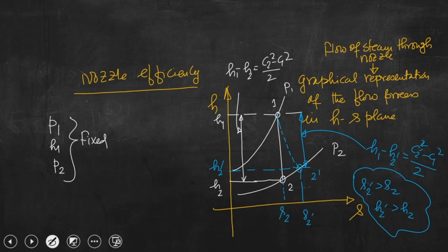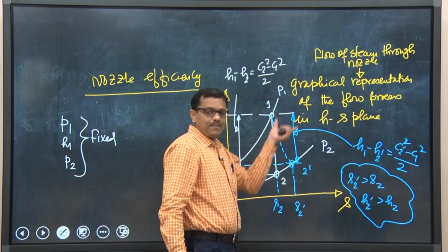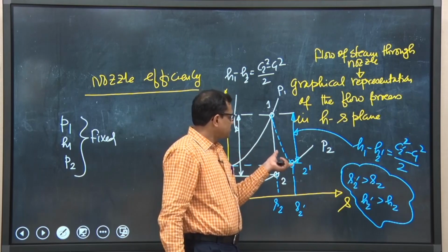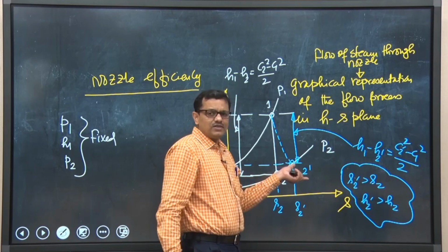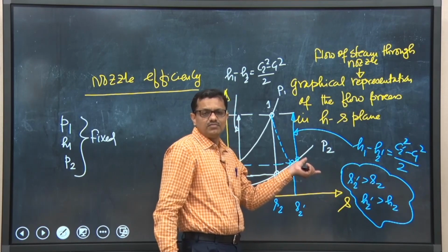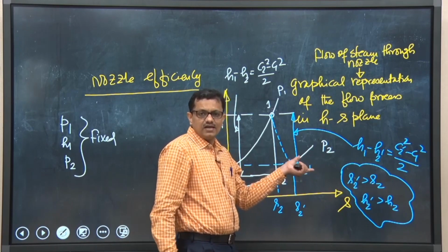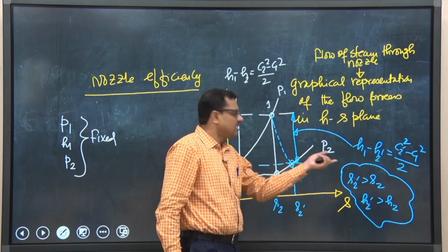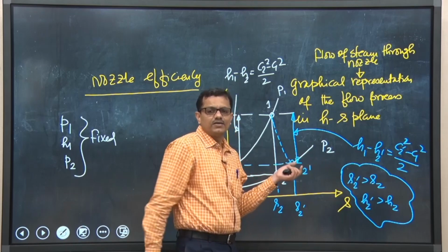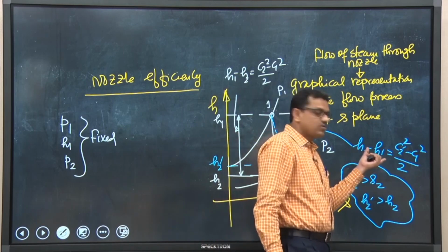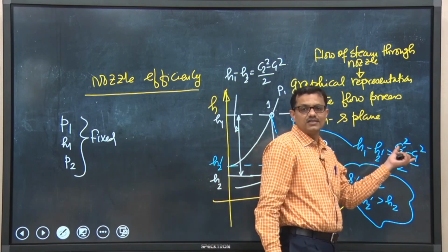So, knowing all these three quantities, if we map the process in this HS plane, we can see that the point 2 prime is going closer to the x equal to 1 line, the dryness fraction becomes higher, and steam temperature increases because of the frictional effect. But at the cost of that favorable aspect, we are going to have compromised velocity at the exit of the nozzle.